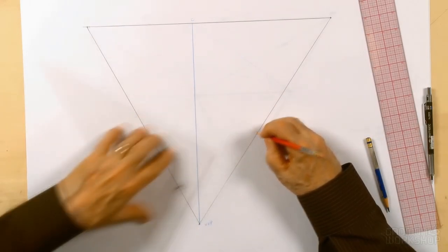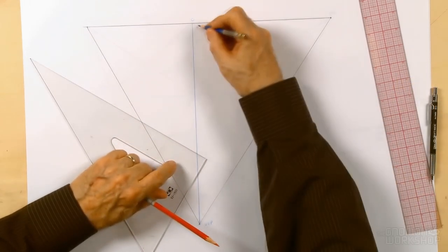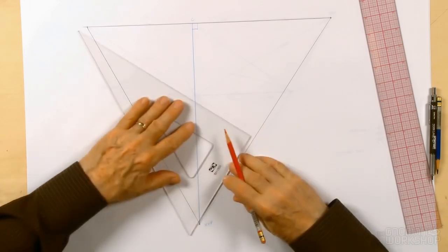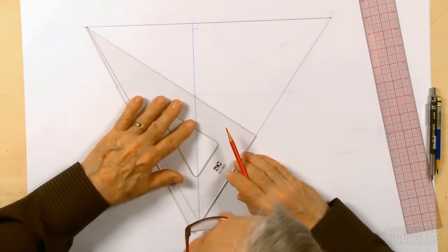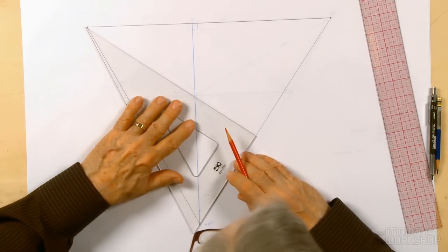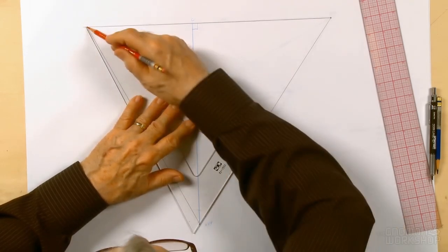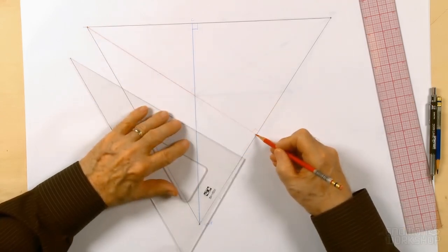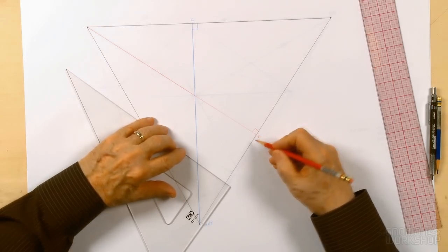Okay, the next step in the process, I would then draw a 90-degree angle relative to this right horizon that goes through the left vanishing point. By the way, let's indicate that this is a 90-degree angle here. This 90-degree angle goes up through the left vanishing point. It has to be 90 degrees to this line. See, there's only one place where that will work. Move this to a position where a 90-degree angle goes through the left vanishing point, like this. That gives me a 90-degree angle right here. And for the sake of talking about this, I'm going to call that point A.